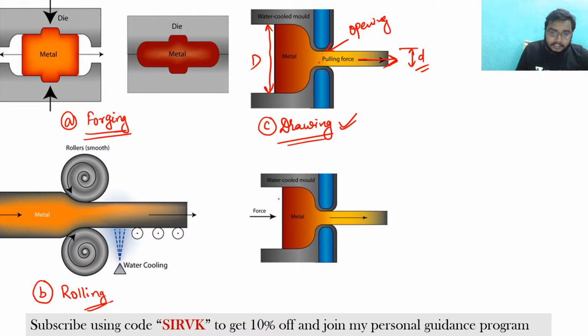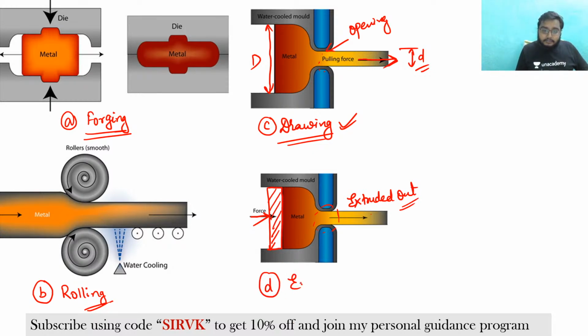Next thing, suppose you take a piston. Suppose this is your piston, and with this piston arrangement you are giving some kind of force to this metallic part, and it is moving out from this small opening. So again, this is a small opening, and hence we can understand that the metallic part is getting extruded out. This process is known as extrusion.